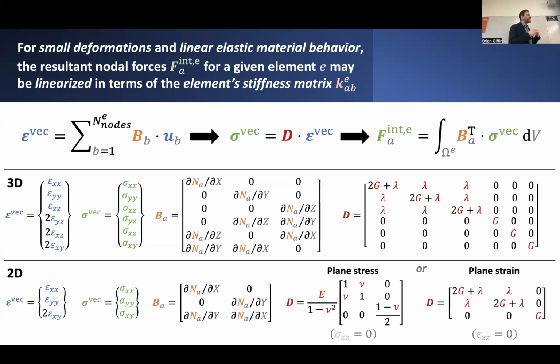If we assume that linear relationship, then it suffices to write it out in the format of a strain displacement matrix, or strain displacement operator, which we called B. And we provided explicit expressions for what this B matrix might involve.